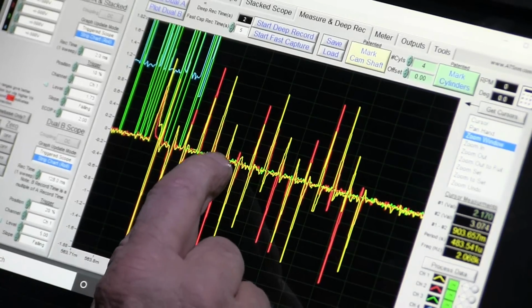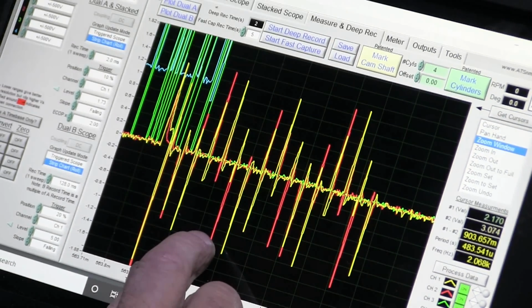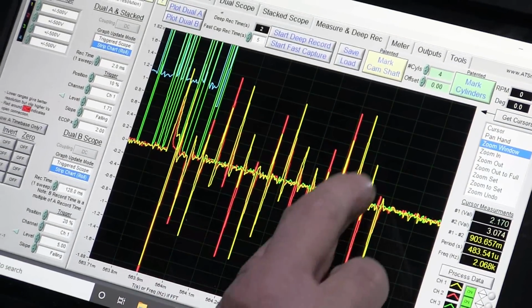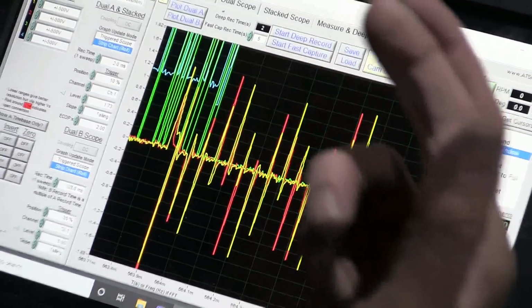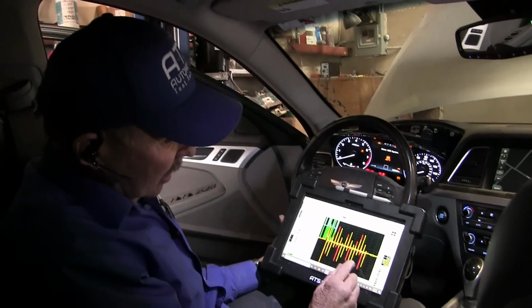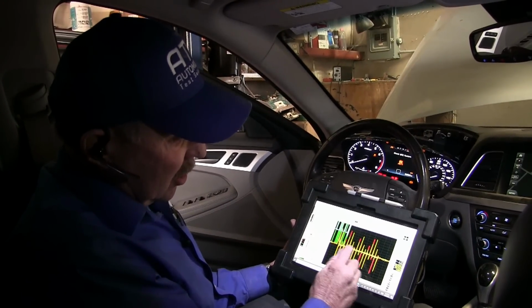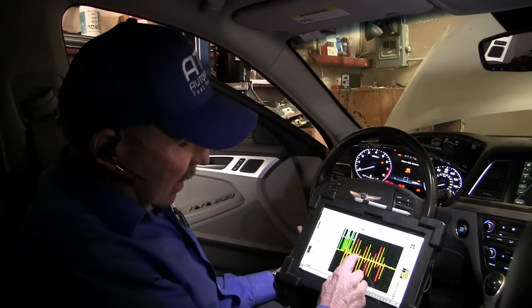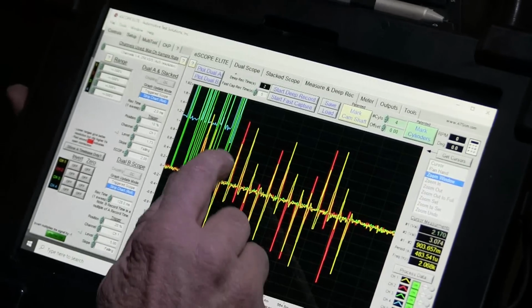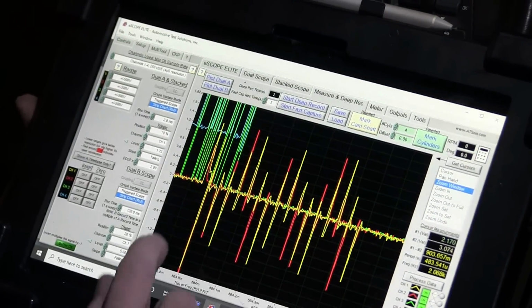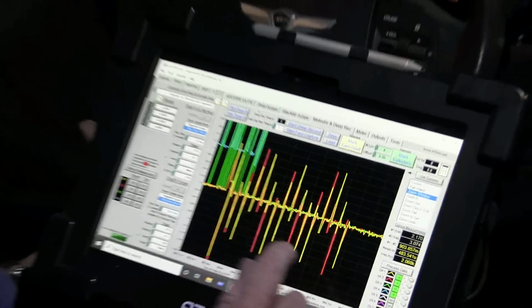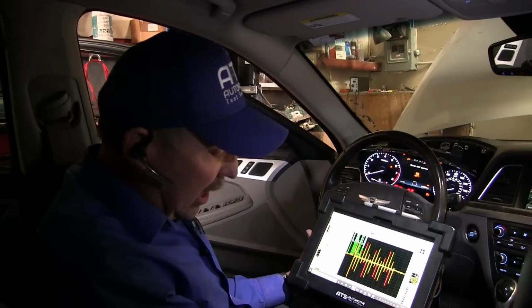Second off, notice that I can have a yellow rise with a red fall, and that means that these wires are not grounded together. Since I'm having two differential potentials and I can see them, these two wires, the twisted pair, aren't shorted together. And then I have a voltage that's going below ground and one that's going above. Now this is just noise. This is not a CAN data pack. So we have a CAN C failure. There's no question about that.